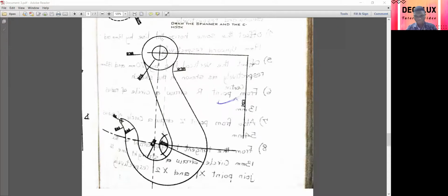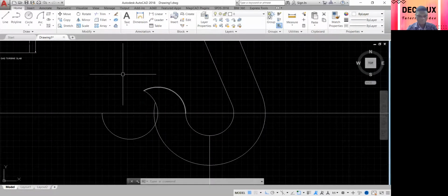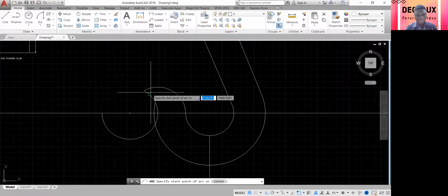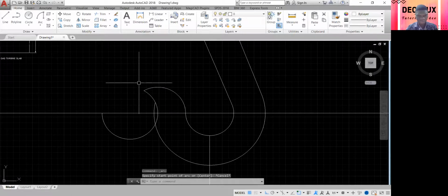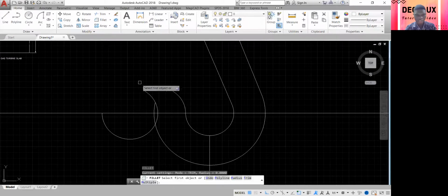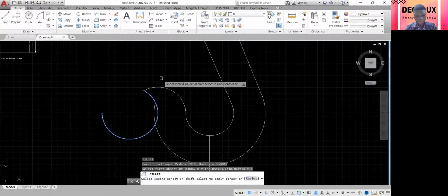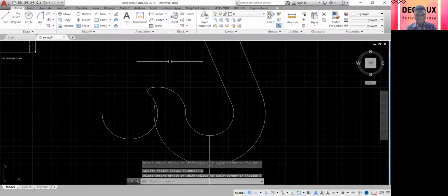So, and what is that? I'm going to pick my arc or circle. But anything I'm going to pick, whether arc or circle, must have radius in it, so that the radius is going to be 6. So that is the first thing I want to have. Let me see if I try fillet, because fillet also works. Radius of 6. Yeah, that is another way.